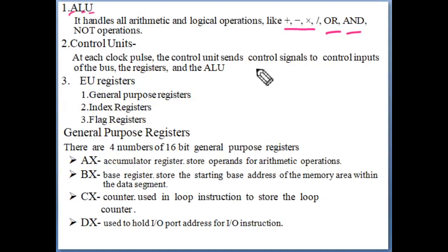It has an instruction decoder that decodes the opcode, and after decoding it generates control signals. For example, if the opcode is add, it instructs the ALU to perform an addition operation. According to the code, it generates different signals. They may control the ALU, or the registers, or the buses. So these are the operations it performs.